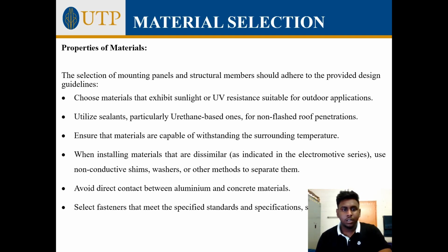The selection of mounting panels and structural members is important based on the provider design guidelines. Firstly, choose materials that exhibit sunlight or UV resistance suitable for outdoor application. Utilize sealants, particularly urethane-based ones, for non-flash roof penetrations. Ensure that materials are capable of withstanding the surrounding temperature.